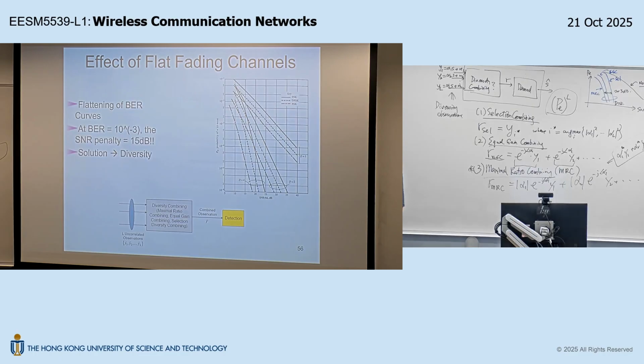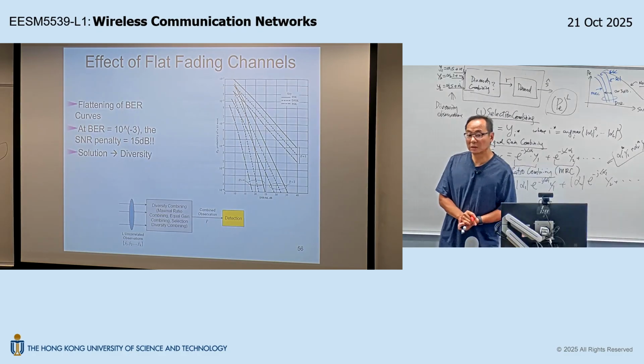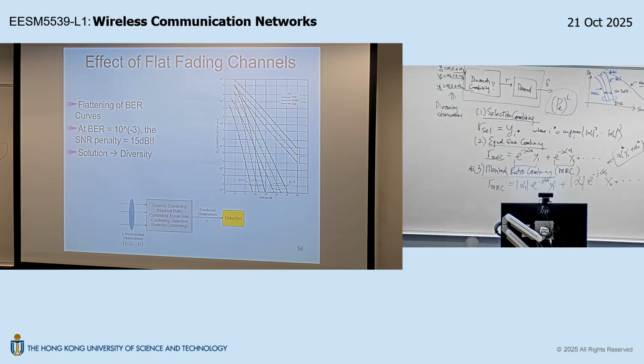So how do you do a channel estimation? An easy way is that the estimated channel by the receiver will simply be given by, if I have n such symbols, 1 over n summation, just take the mean. And that can give me the estimate for the channel. By the way, this is called least square channel estimation.